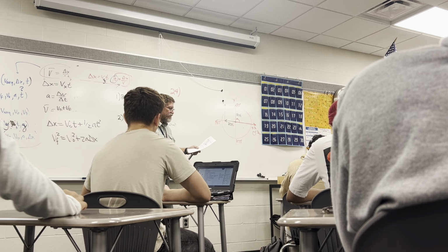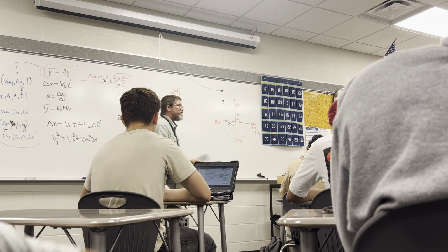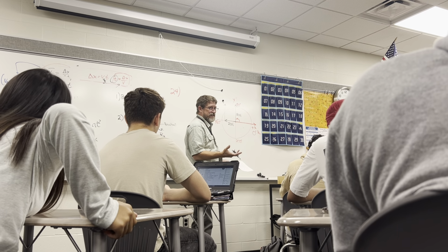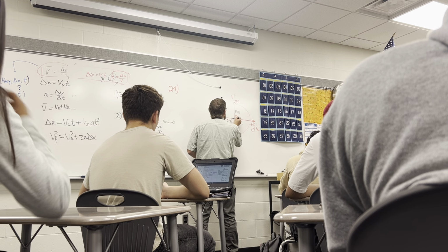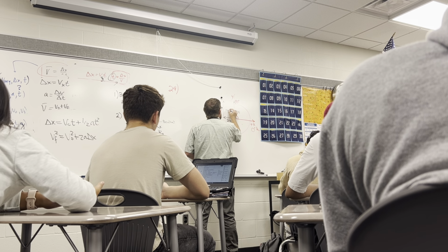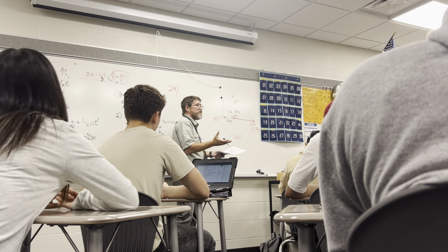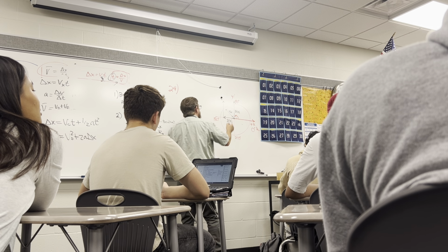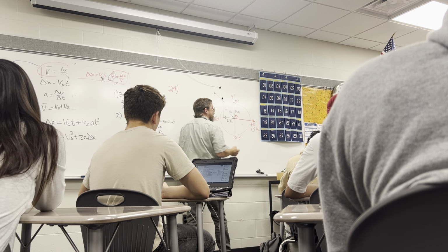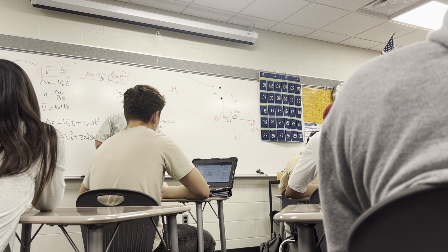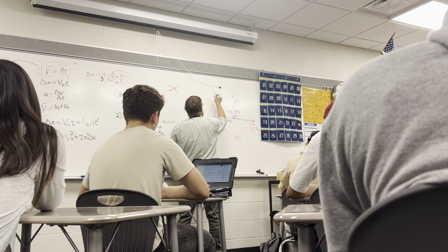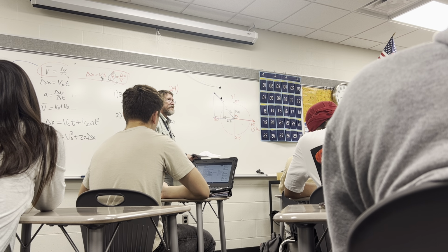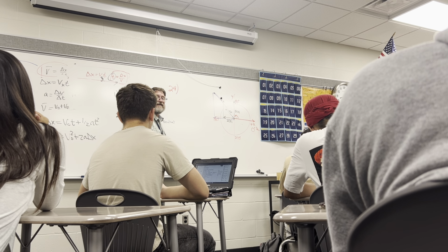And then there's 25 newtons at 135 degrees, and it says 45 degrees northwest. I hate northwest, southeast, any of those things. Just give me 0 to 360 and I'm happy. 135 is around this way, but it is at a 45 degree angle like this. We have 25 newtons. So these 3 forces are pushing it left, that way, and at an angle like that. When we add this head to tail, we're going to ultimately put it out here and just add it to the next guy. What we are looking for is a giant triangle that looks like this and has 2 sides. Because it's a triangle, well, 3 sides. But 2, an x and a y, and a hypotenuse. So here's how you do this.